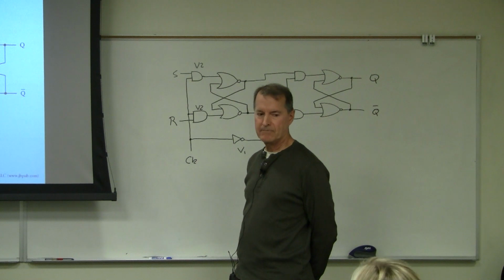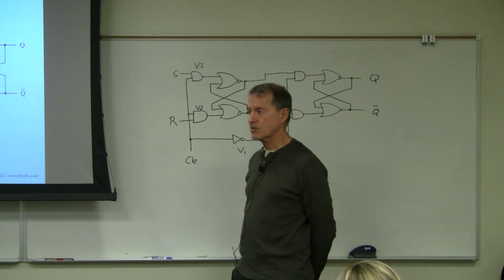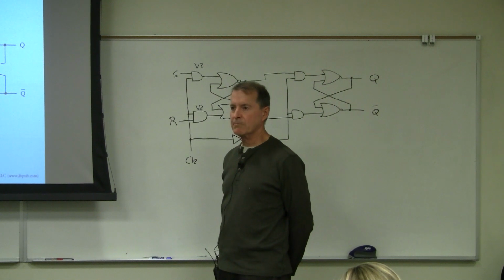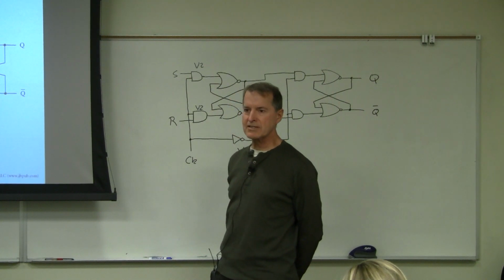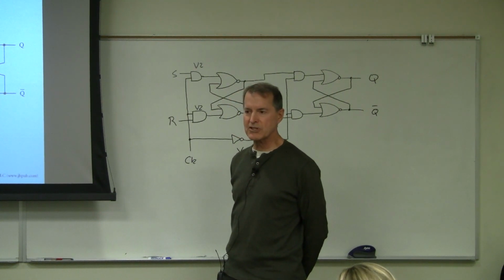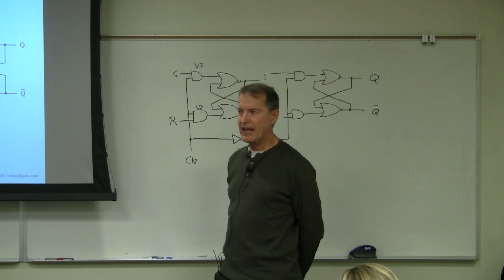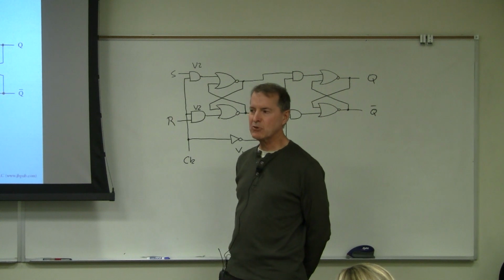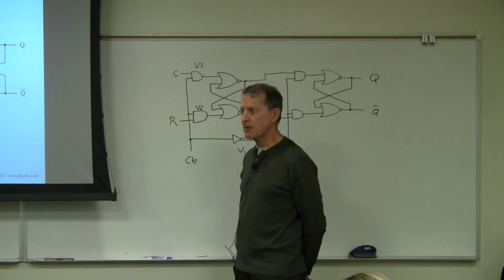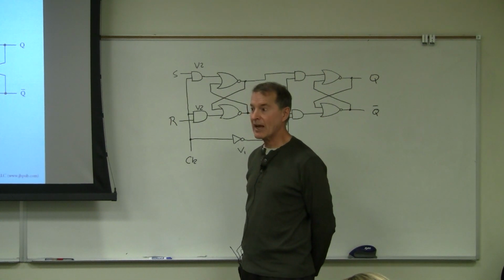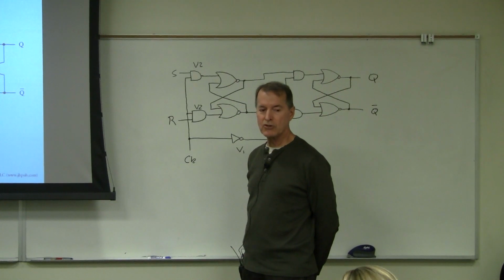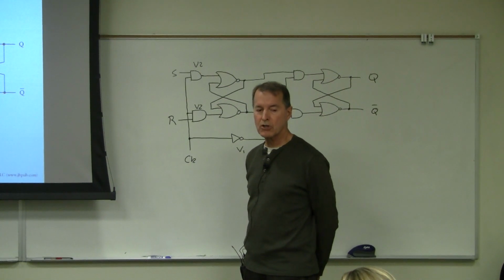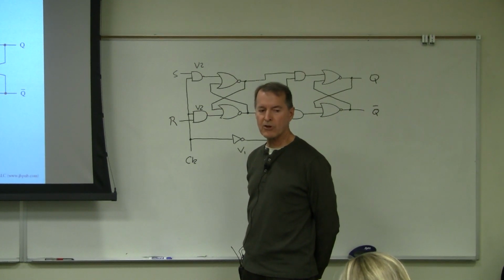For the first one, when we have x and y, you need to make separate ones for x. Yes, that's a good question. There was one of the exercises in the book, a switching circuit, that had 4 inputs and 2 outputs. Anytime you have 2 outputs, you have to have a separate circuit for each output. So you should show 2 4x4 Karnaugh maps.